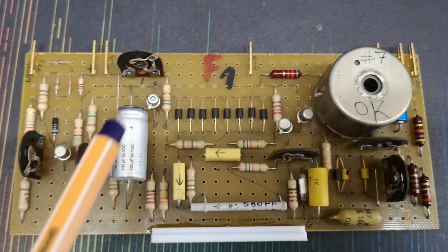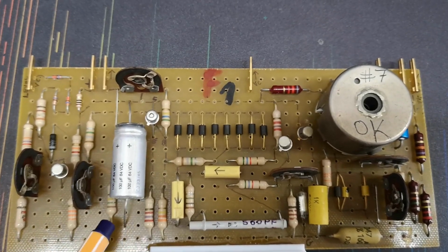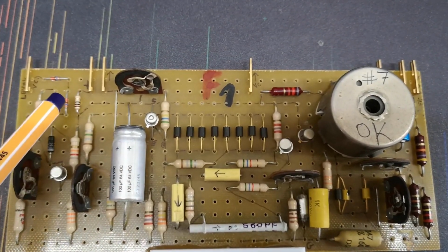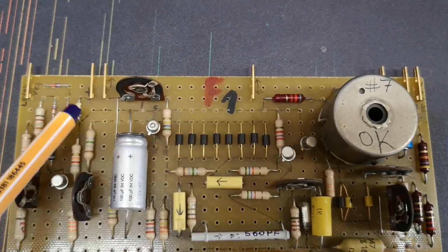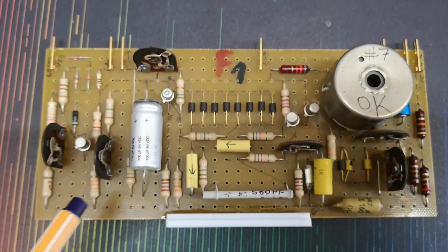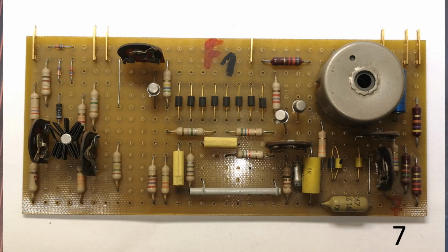See the changes I did? So I got a local capacitor on the supply and a series resistor of 10 ohms on the 24 volts input. Let me show you here. This is the original module without the modification, and you see the capacitor and the resistor is completely gone.